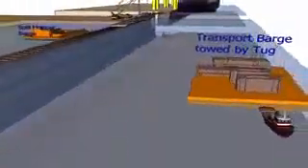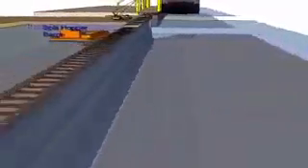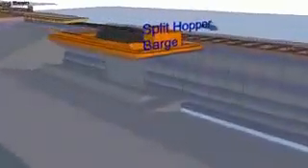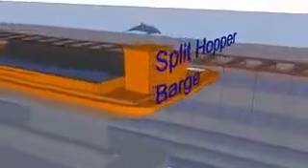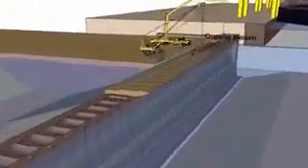The quay wall is constructed using precast reinforced concrete hollow blocks that weigh up to 160 tons. The blocks were cast in the on-site precast yard and loaded onto barges at the temporary loading jetty that had a 200-ton capacity gantry crane.